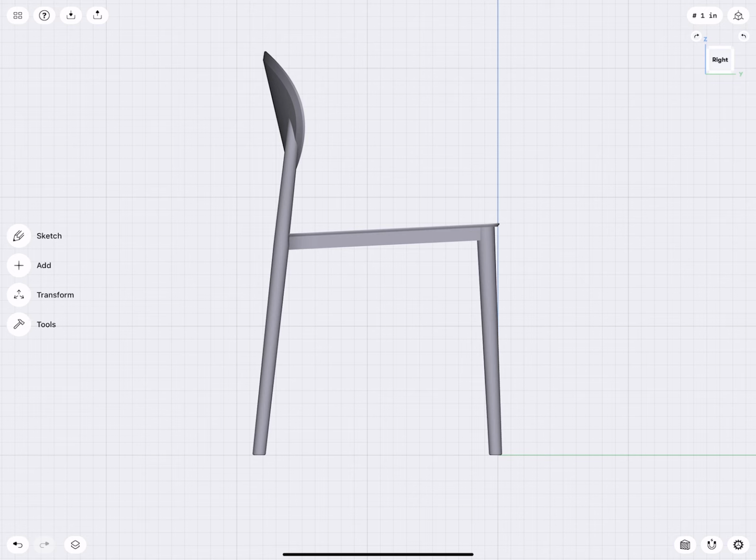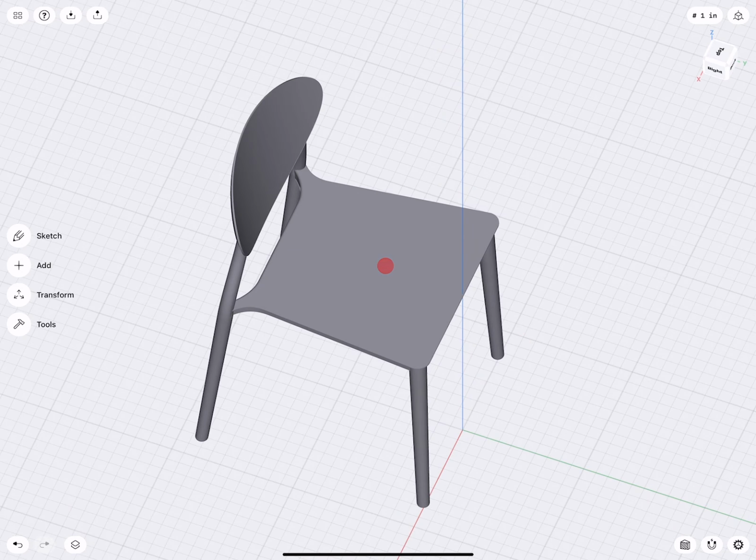Before we continue, a really good piece of advice is to take a look at what we see and not get discouraged by the complexity of an object. What are the individual building blocks? So we have front leg, backrest, seating surface. Seating surface has a transition, rounded edges. That looks all pretty complicated. It's not really. The seating surface is more like a trapezoid. And then the rounded edges we do via a rounding command, the fillet.